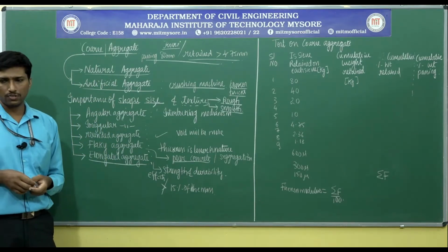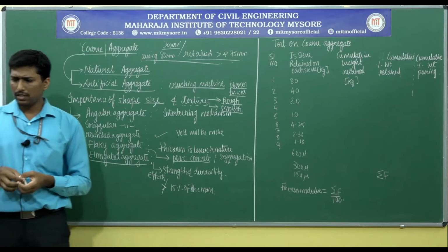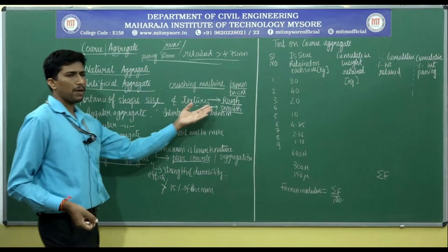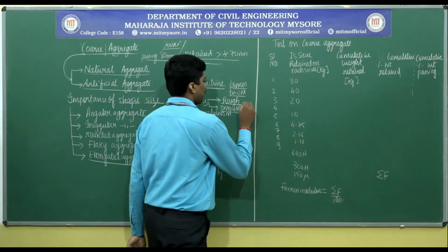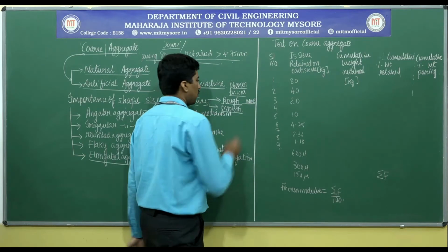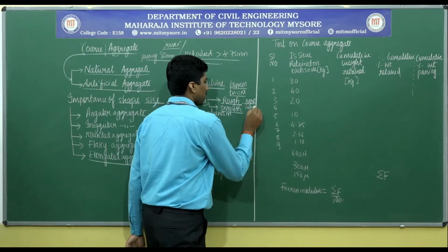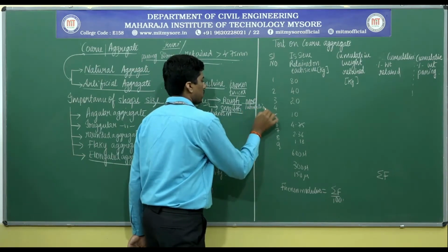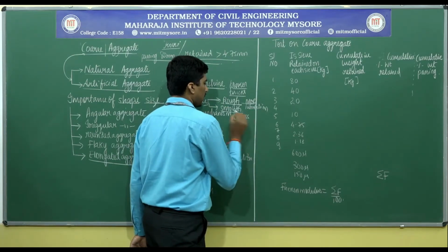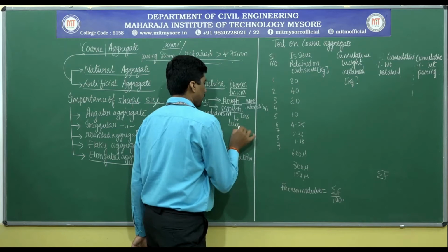Therefore, texture is also a critical concern related to the usage of aggregates. Another thing is, higher surface area requires more space for lubrication, more lubrication, whereas the smoother part requires only a lesser amount of lubrication.